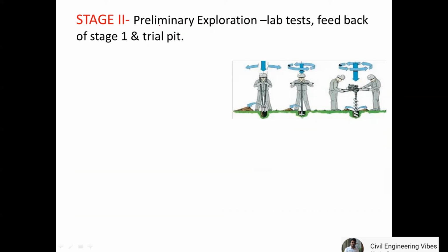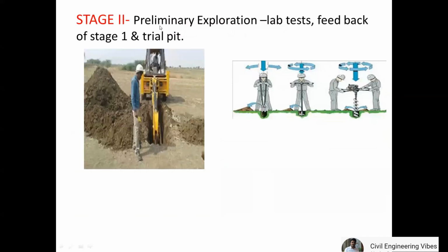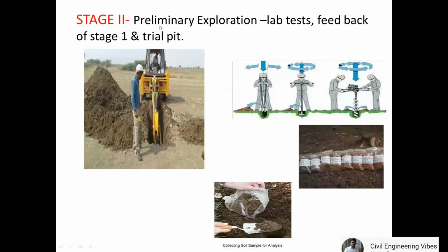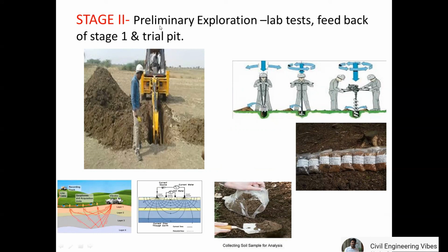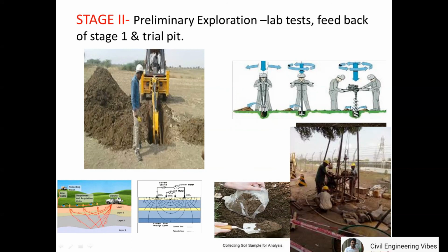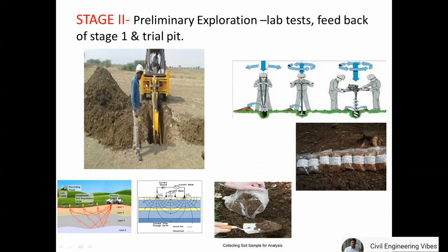For fulfilling the values of design parameters, laboratory tests are preferred with remolded samples because of the cost cutting compared to obtaining undisturbed samples. Boring for the investigation is done by hand auger or mechanical auger or by wash boring methods. By doing so, the approximate thickness of the strata, groundwater level, and depth of the rock are known.